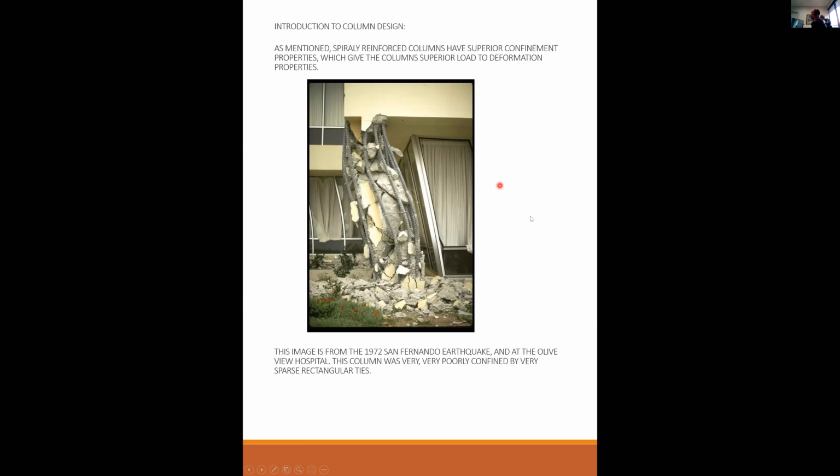And every time the building bounced from side to side, the cracking would be on one side, then the other, then that side. Pretty soon the cracking gets so severe that big chunks of concrete just fly off. It's called the cover concrete, and it will spall off into this big pile down here. And then as it just keeps going back and forth, it basically disintegrates. Okay. Did that answer your question?